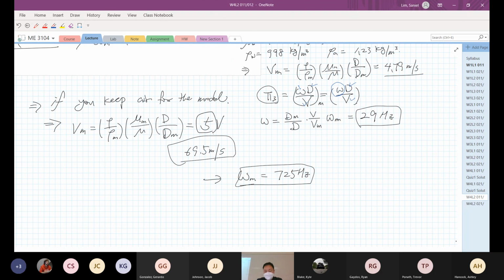So it's always about finding the optimal range of the modeling conditions. Something like scaling is one of the biggest ones. You want to minimize it, but also all the variables in the system, like velocity, should not exceed a reasonable range. You don't want to measure something like 100 meters per second speed within the model at small scale, on that tabletop, right? That's one of the criteria when you design the model and the experiments.